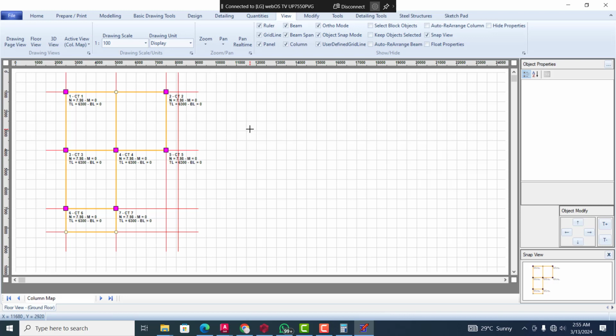So by looking at the layout, it gives you pictorial information of what really is happening, which of your columns are critical, which ones are not critical. These are how you do inspections, to satisfy yourself as the designer that yes, I'm designing correctly. Because these things are just softwares built by men. But that should always not take away your competence as an engineer. You must learn to know how to inspect your layout and be satisfied that you're okay.